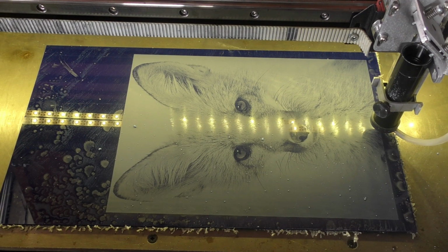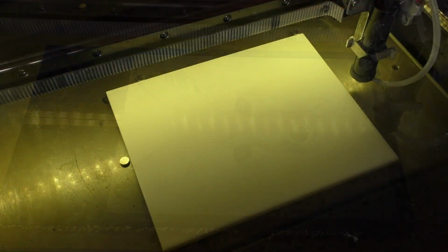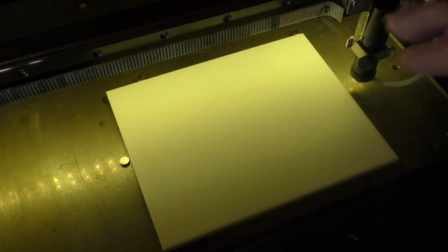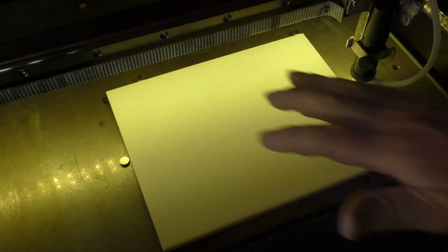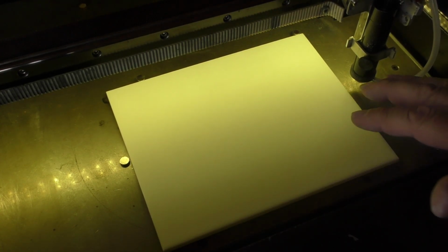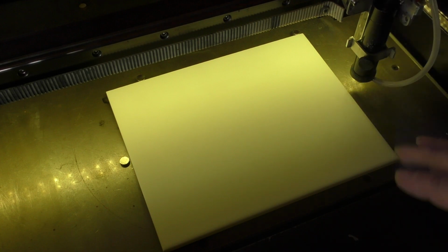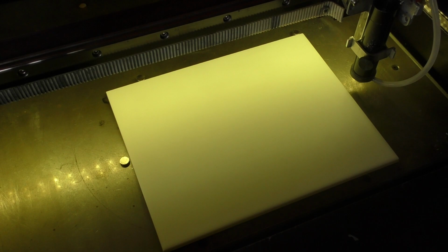21 minutes 34. I've increased the power from 25 to 50 because this is a different material. I've got titanium dioxide on the surface here, on the surface of a white tile. And so we're going to attempt almost the Norton tile method of creating a dark image at 1000 millimetres a second.